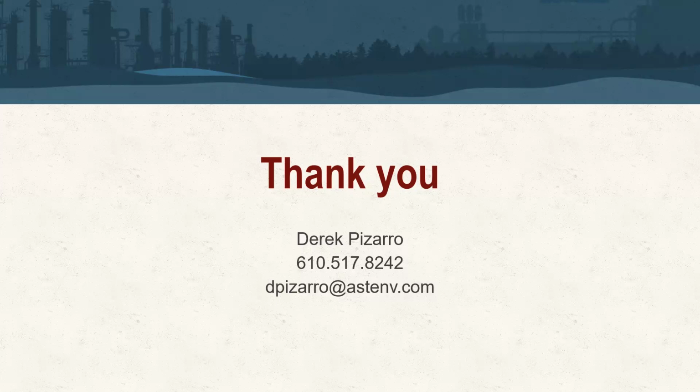You're talking about contaminants that are very unusual in some cases, whether they're in situ groundwater or in situ soil. They are not something many practitioners deal with, and especially in the case of a metal like arsenic, which can also be an organometal, there's a lot of parameters geochemically and co-contaminants that could affect their treatment. So I would say, at least in my opinion, probably more so than any other organic contaminant, heavy metals treatment certainly requires a bench scale study for each site, and that would include both soil and groundwater if it's a saturated zone.